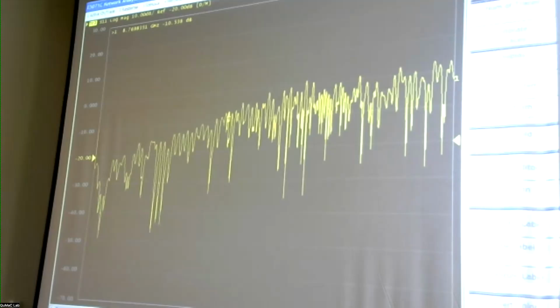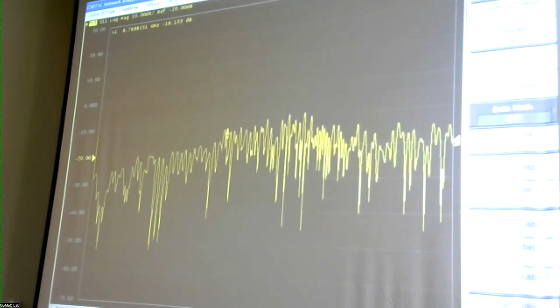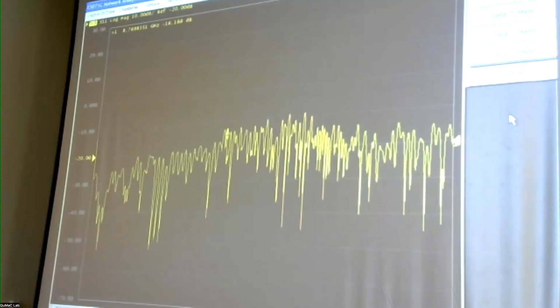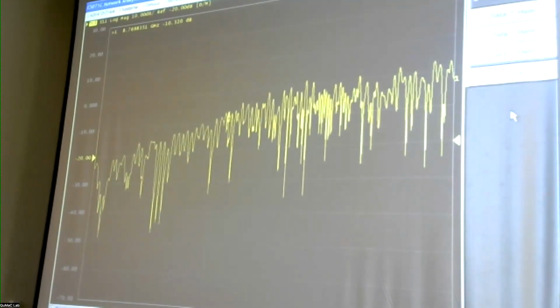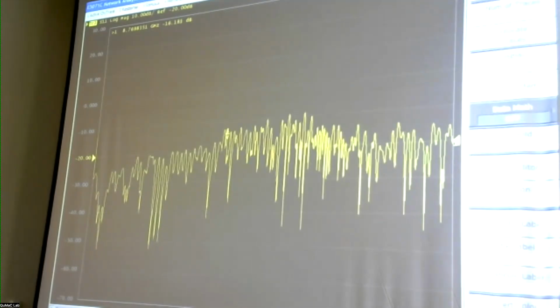Let's check first. Wait. Much better. So this is again a feature which has now become a bug. There was this thing called data map, and that was set to data divided by memory. That basically is a method where you can save one of these S parameters as a function of frequency and put it into memory. And then you can do operations on the current data. So you have these kind of options.